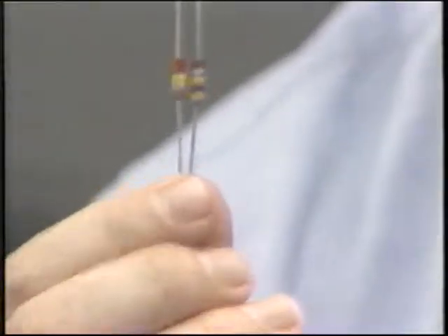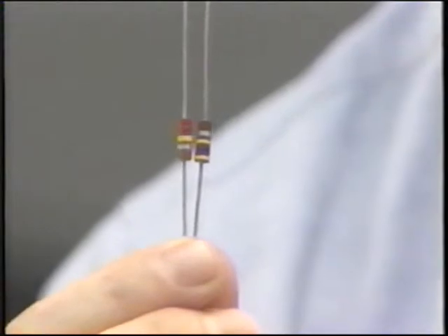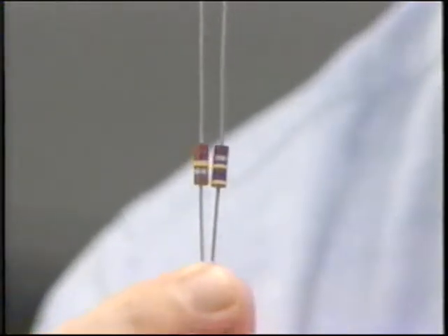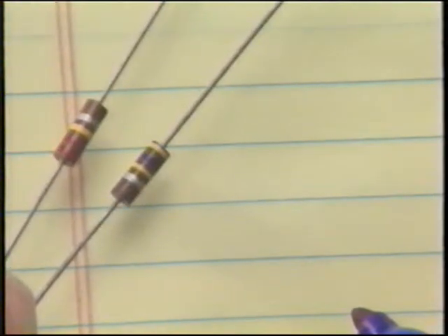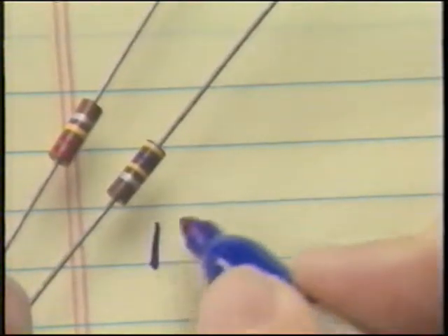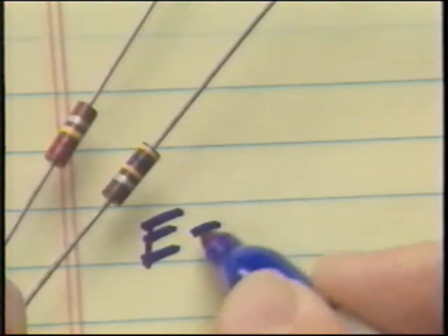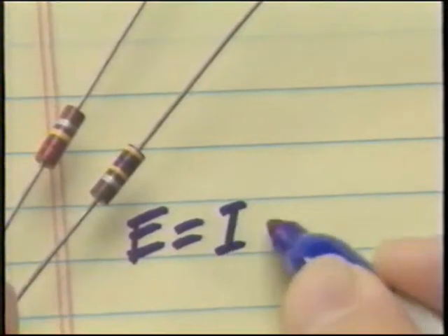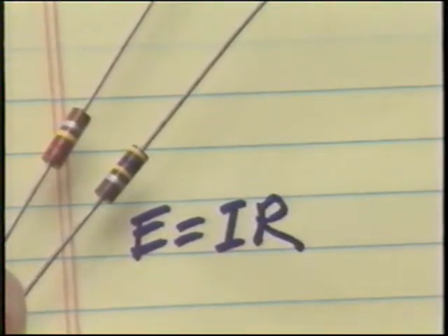Let's get started. You've already seen that resistors serve the same basic purpose in AC circuits that they do in DC circuits and are used just as frequently. While the voltage across and current through a resistor in an AC circuit constantly change over time, the Ohm's law relationships among voltage, current, and resistance still hold true.